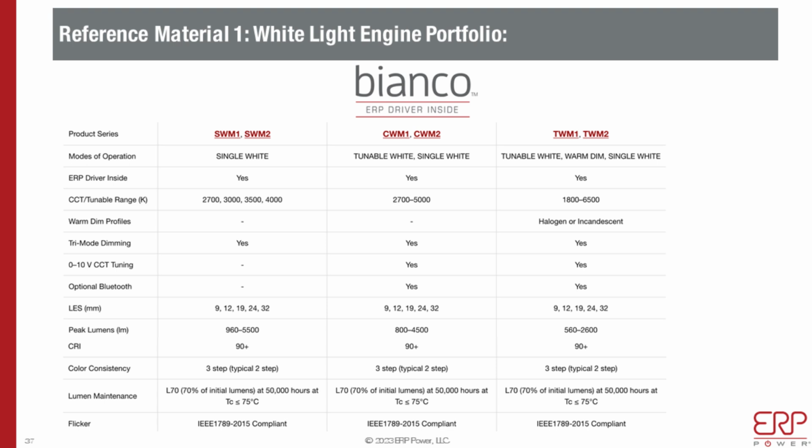What about the maximum wattage? Yeah, so maximum wattage, again, depends on the lumen and the efficacy of the puck. So TWM2, think of it as 100 LPW. So let's say about 24 to 25 watts. That is the maximum on TWM2. But you could go higher again. It all depends on the LPW.